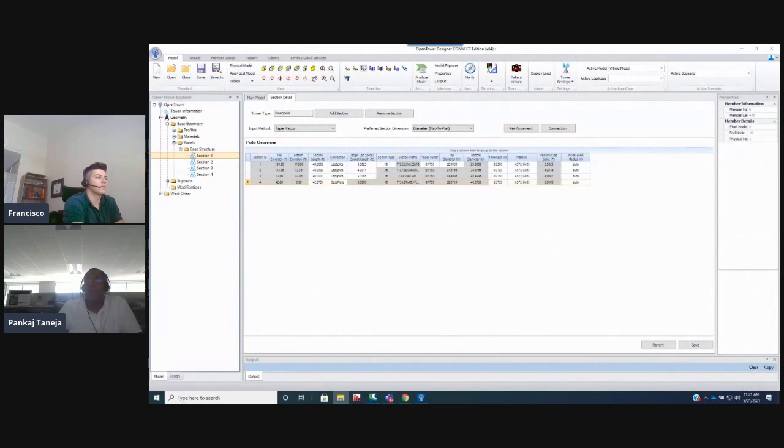TIA-222-H has a different concept. The different concept means that when we ask what the bend radius is, there is now a new force coefficient calculation based on the bend radius ratios. That was a good thing, but how will users do it?